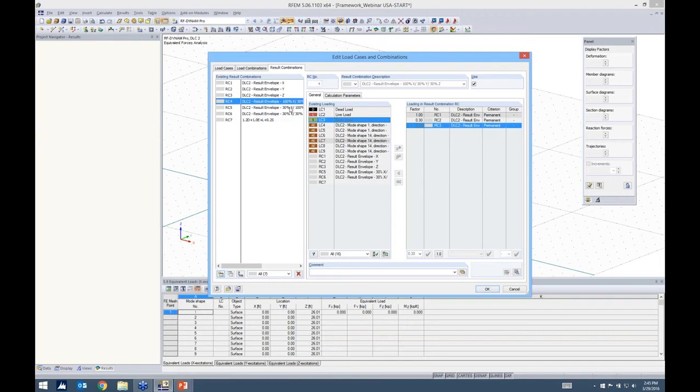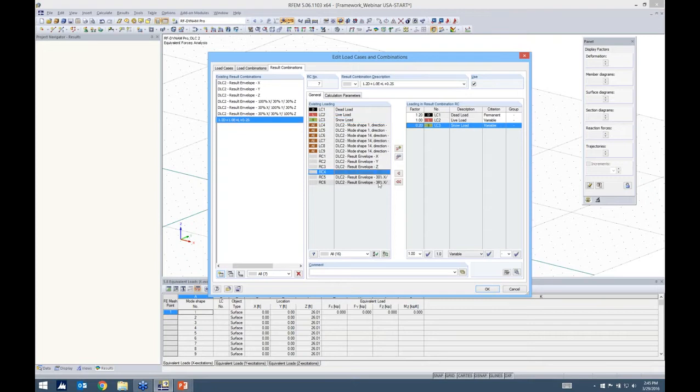So we have our earthquake loads according to the 130 rule, but the question is, do we need to create a result combination with this first result earthquake loads, then another one including the second one, and another one including the third, since we don't know what the worst case is? But the answer is actually that we can use the program to help us here. If I go ahead and select all of these 130 rules, there's a button here called Add Selected with Or.